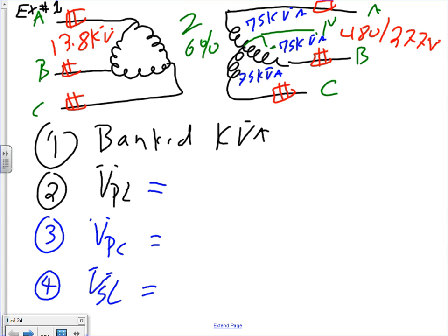Okay, so this is phase C. So let's look at what we have. We have a delta Y transformer. On the primary side, we have phase A, B, C. We have 13.8 kV with the fuses. On the secondary side, we have a Y, center tab. Z in the middle is the impedance of this transformer. It will help us calculate the short circuit. On the secondary side, we need the fuses. We need to size the fuses as well as the circuit breakers, the fuses as well as the feeders. The secondary is 480. Each one of these three transformers is 75 kVA.